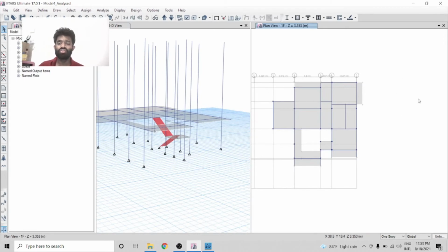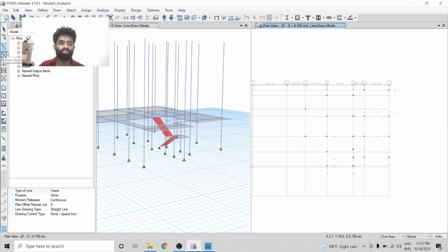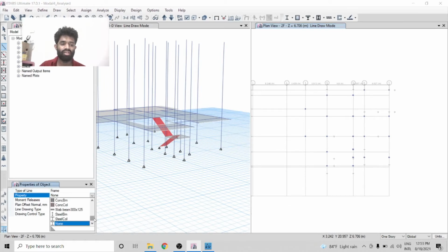Now I am going to draw the second floor. This is the first floor, and I am going to the second floor. The second floor is empty because we have these options for one story, so I will pick my second floor, or simply rooftop plan, and I am going to draw the beam arrangement of that rooftop plan here. I have already selected the non-beam type, so I have to change it to the beam size option B225 by 300. So my beams are like this, and I quickly draw them all.